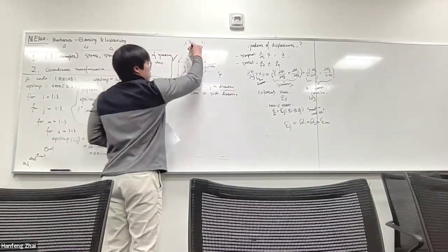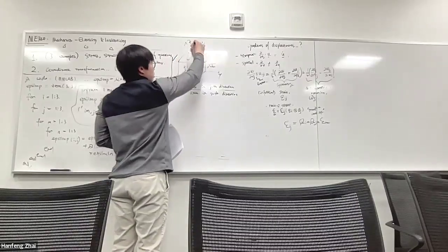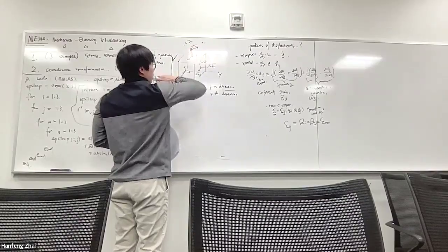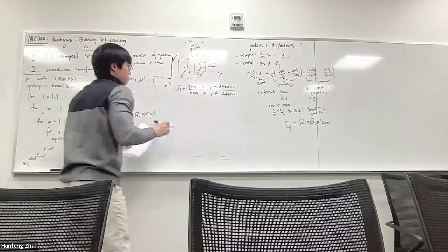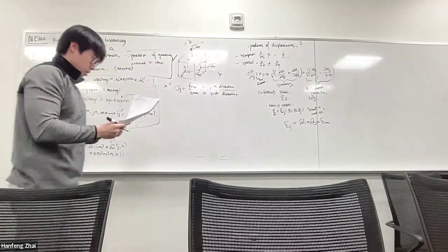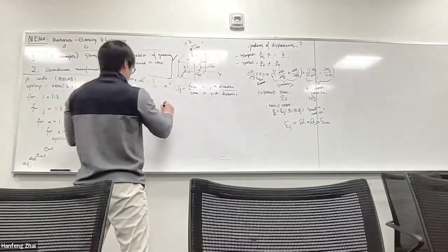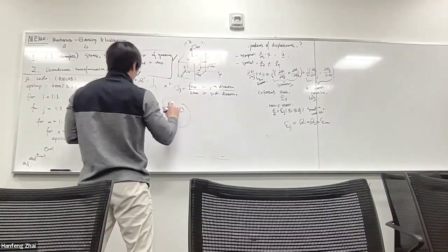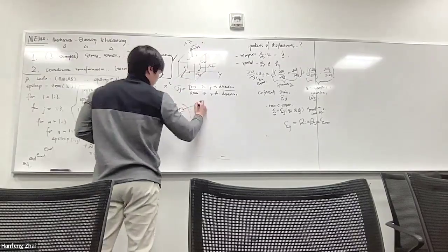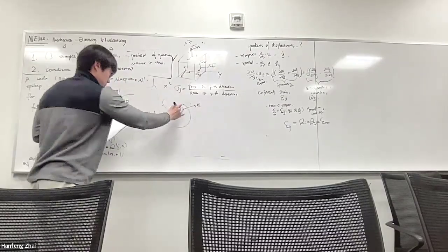And this stress tensor component is lying on the z surface and pointing towards the z direction, so it's sigma 33. And so on. And for any random continuum body, if you take a small piece of the surface, you define the surface normal direction as n. It's the normal direction of this surface.